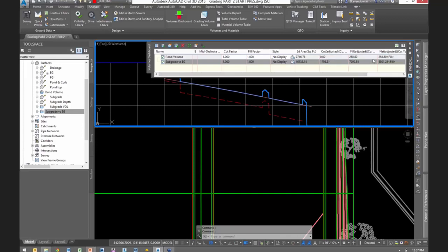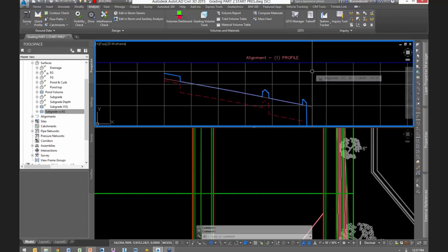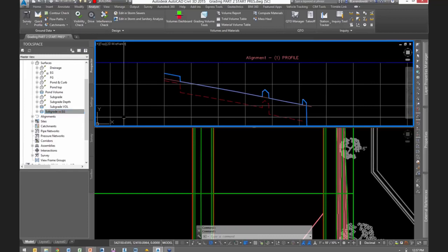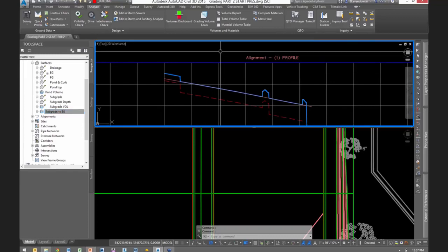Okay. So this is why we set it up this way. It's all about dynamic relationships between all these surfaces. I created, what do I have over here? 4, 5, 8, 9 different surfaces in here. We talked about in the first part about turning down tessellation spacing and turning surfaces off. Okay, you're making a lot of data in here. You have to keep that data turned off to make this work well.